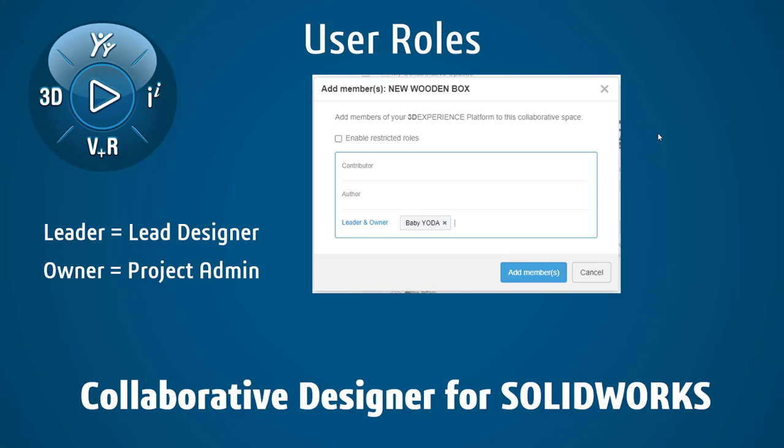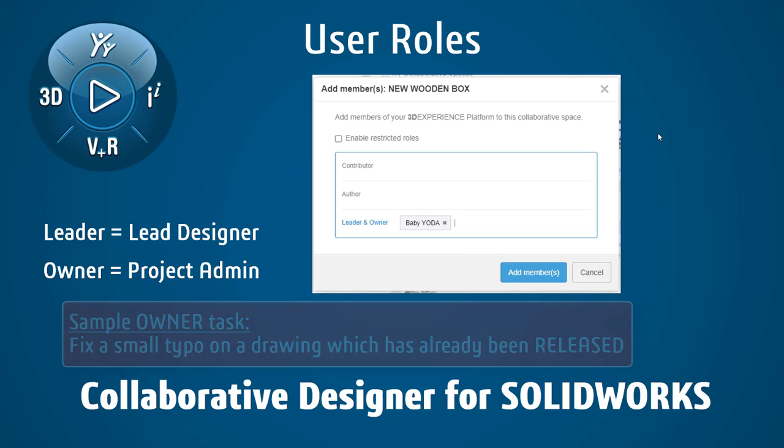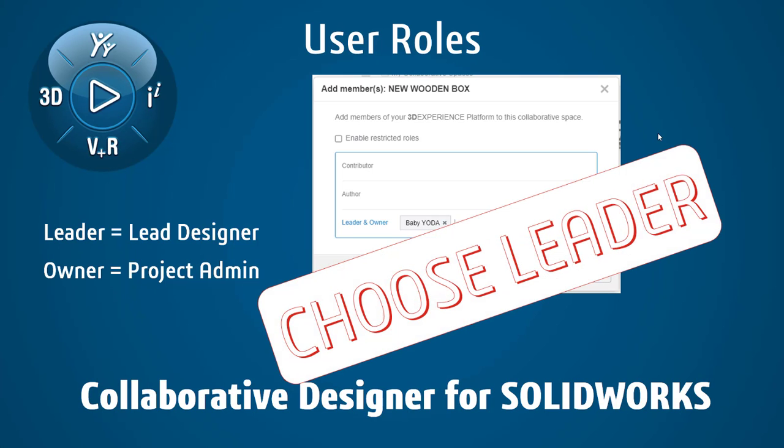The owner, on the other hand, is more of a super user account inside of this collaborative space. This is someone who doesn't have to adhere to any of the rules of the data management scheme and really only ever logs in when something needs to be fixed. However, the owner is not creating any files in SOLIDWORKS, is not doing any of the design work. So for most of you out there who are watching this video, the best bet is to always choose leader. Whenever you're presented with the option of choosing owner or leader, just always choose leader. That's going to let you do all your design work, and it's also going to let you push the files through the revision scheme when utilizing data management in the cloud.